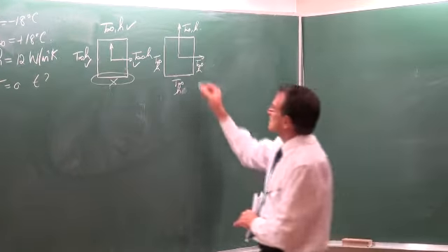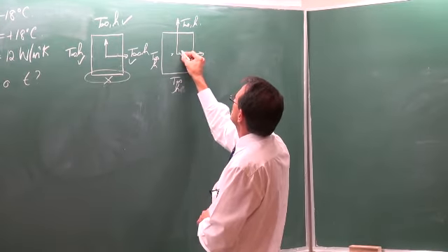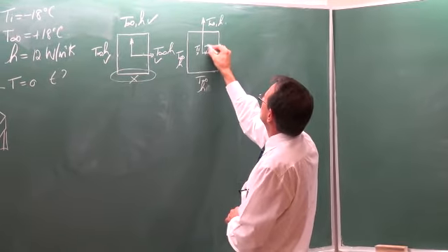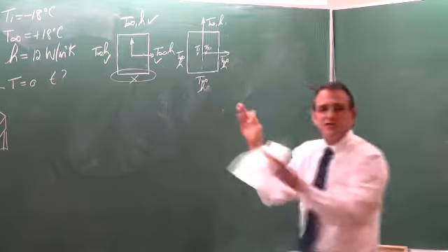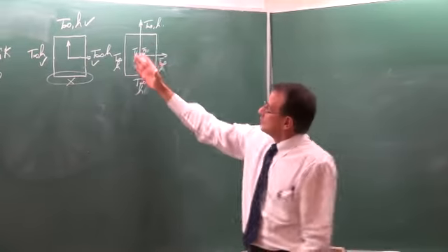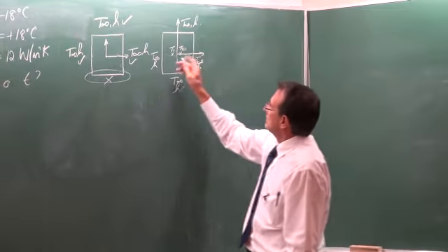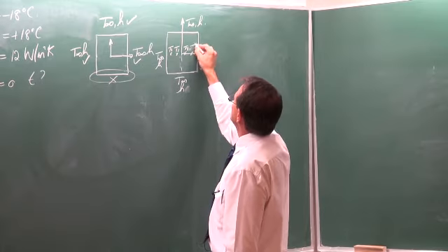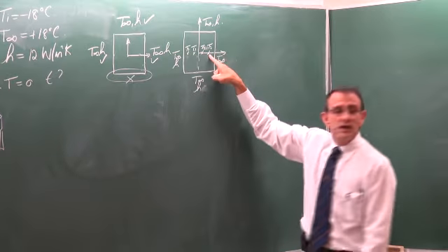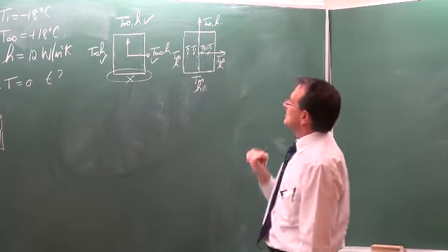If you consider this case, then it would mean that the temperature there and the temperature there would be equal. Do you agree? Because of symmetry. We've got the same boundary conditions on this side as on that side. It would also mean that the temperature there, temperature at point 2, would also be equal to that temperature. There's symmetry around that surface there.